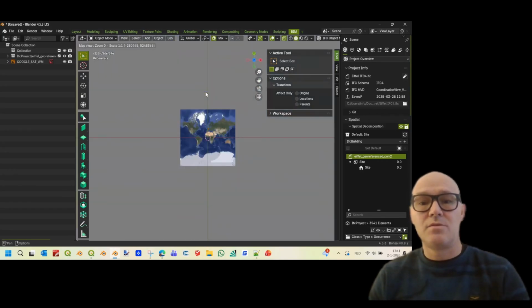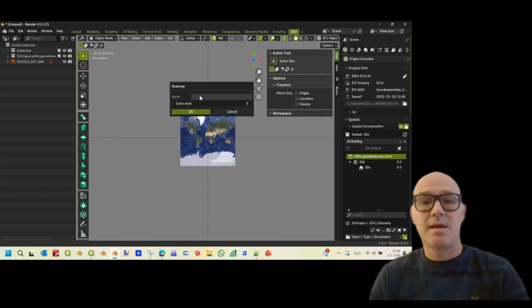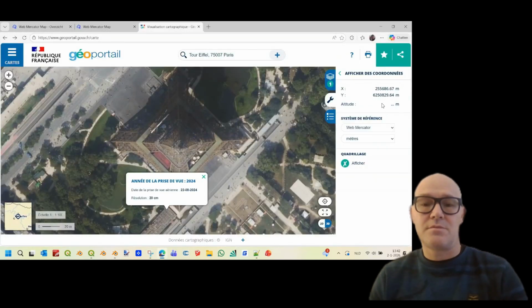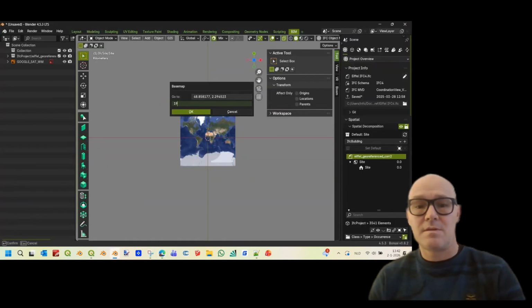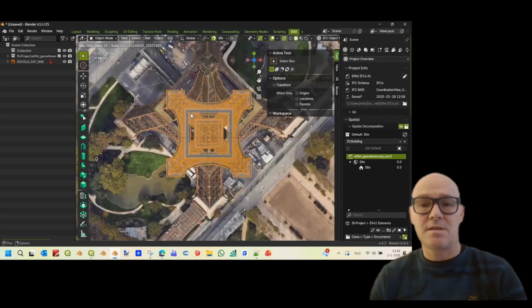Activate the Google satellite, then press G for Google, enter the lon lat value, and enter 19 for the zoom value. This way you get a nice zoomed in view. So here again, the same values. You want to use decimal values. Decimal is the way these systems work, not with seconds.